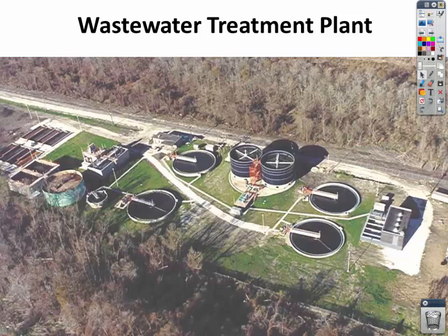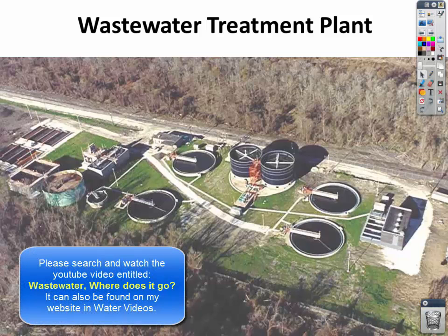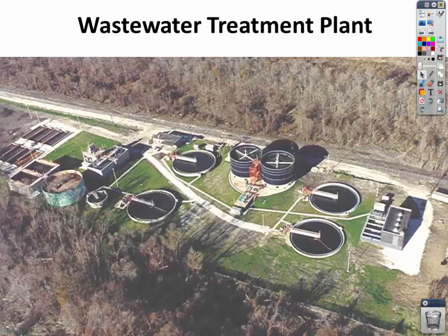Okay, so that's the plant. You'll see it from an overhead view. You see a lot of settling tanks. Just take a look at this and see if you can find primary treatment, the square rectangular settling tanks. See if you can find any aeration tanks where they might use biological treatment. See if you can find any secondary settling tanks, those would be the circular ones. And then see if you can see the creek or stream where the now cleaned water gets put back into the environment. These are all around us. You pass one every day, and this is first world technology.